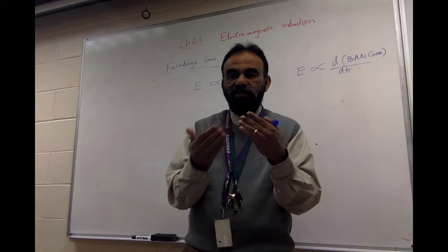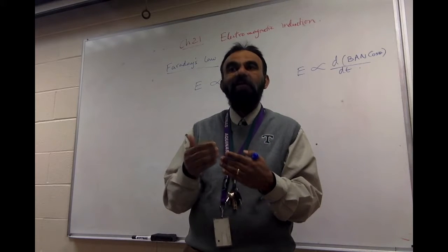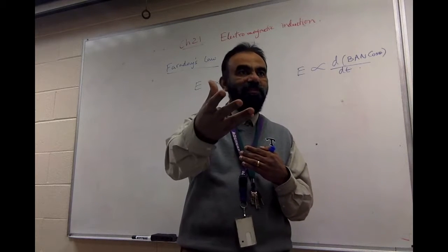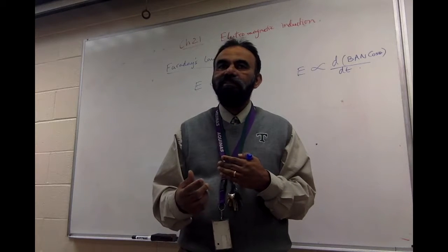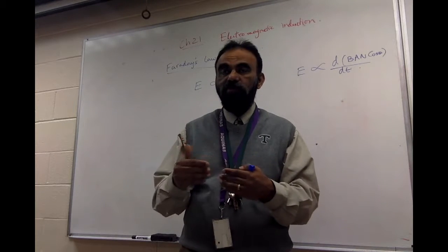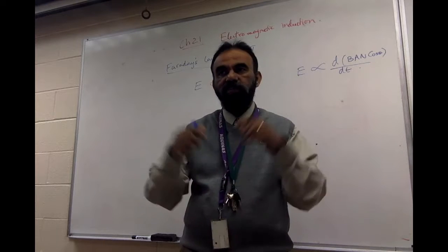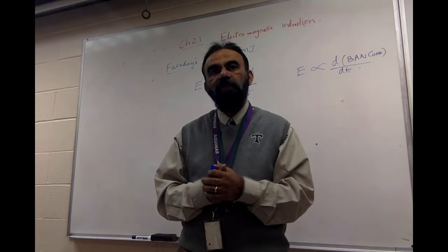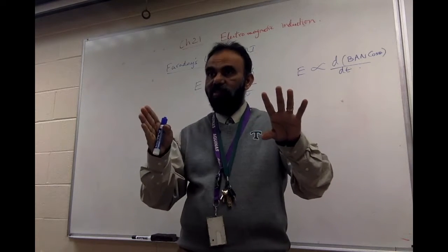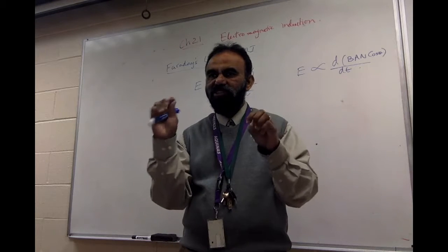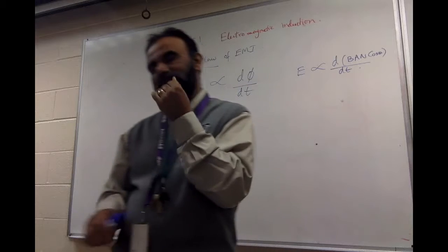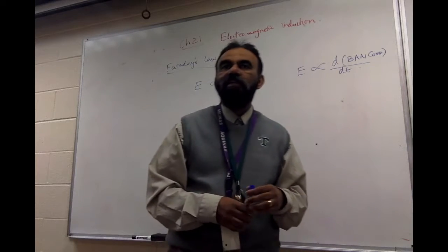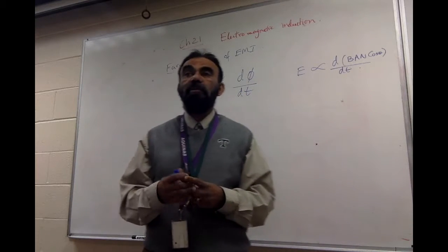It's not doing much. But if you're driving faster, it will create more EMF because it's spinning faster. And that's why even the headlights will change their brightness. Headlights will become brighter when you're driving faster. When you're just idling your car, the headlights are barely lit. However, it's much better these days. But at least what I'm trying to say, or a bicycle dynamo.